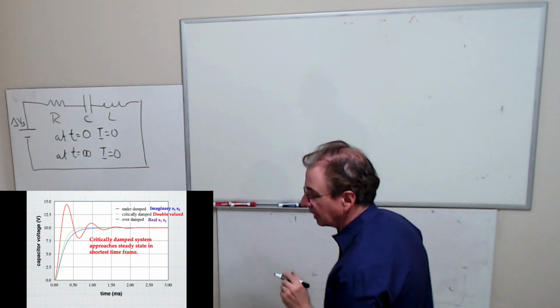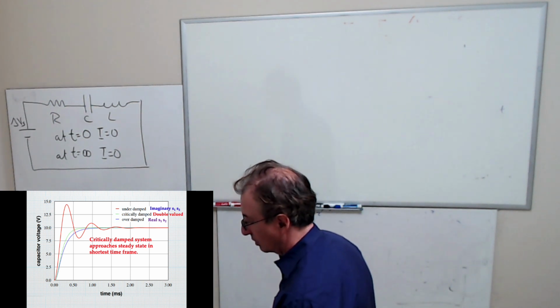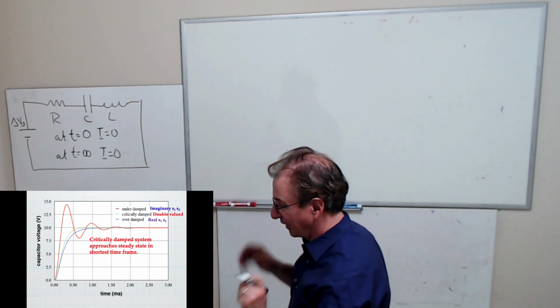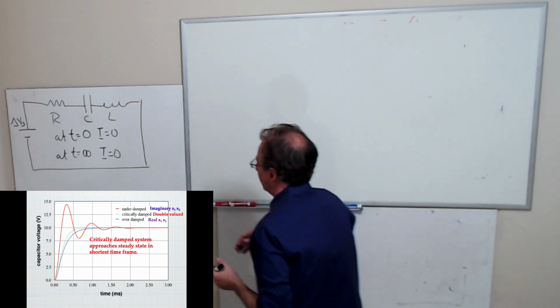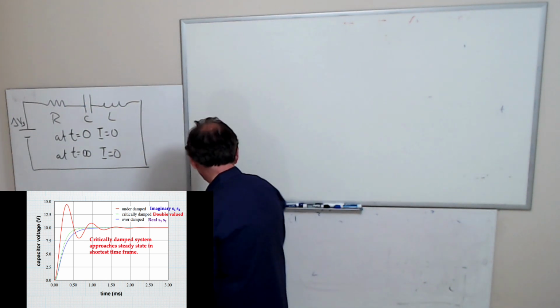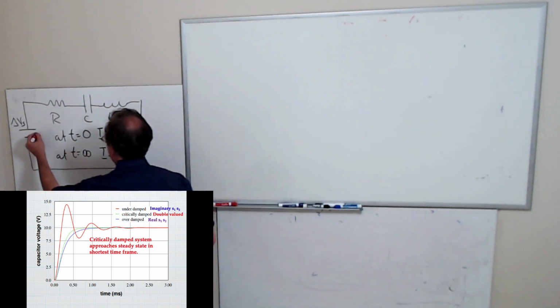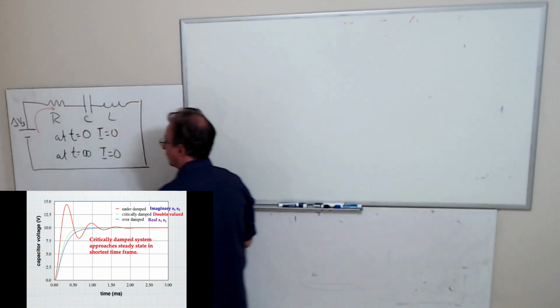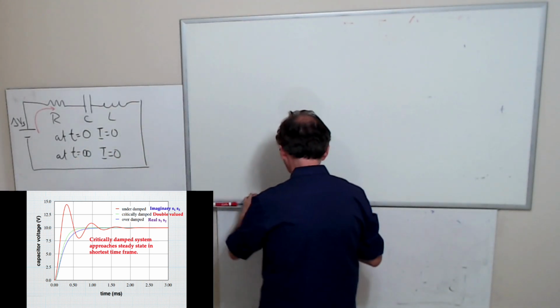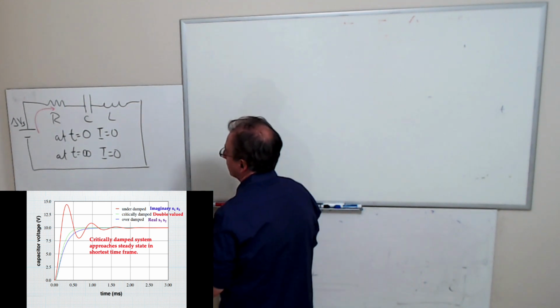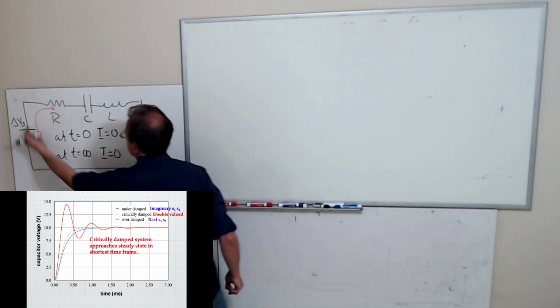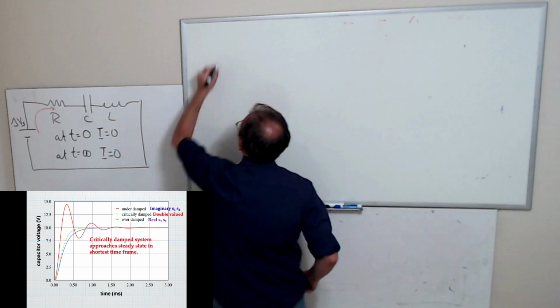And so let me apply the modified version of Kirchhoff's. The reason why I say modified is because of the inductor. I'm going to assume the current's going to be going this way, and I'm going to assume voltage drops in that same direction. And since I am doing that, then I can say I have a voltage gain here, and all these are voltage drops.